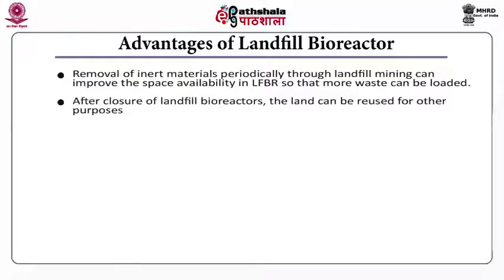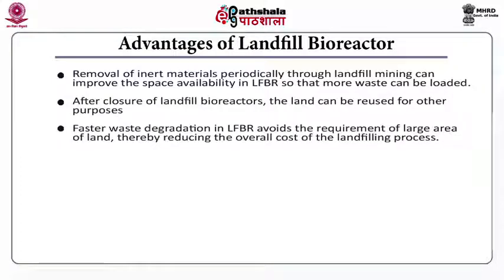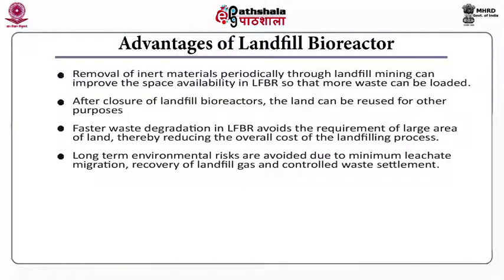After closure of landfill bioreactors, the land can be reused for other purposes also. Faster waste degradation is attained inside a landfill bioreactor, and hence it avoids the requirement of a large area of land. Thereby the cost is also reduced when you use a landfill bioreactor. Long term environmental risks are avoided due to minimum leachate migration, recovery of landfill gas and controlled waste settlement.